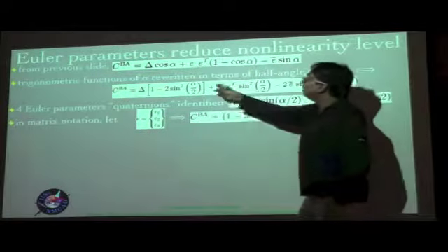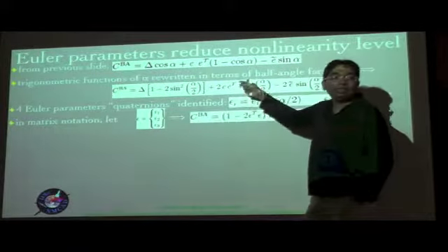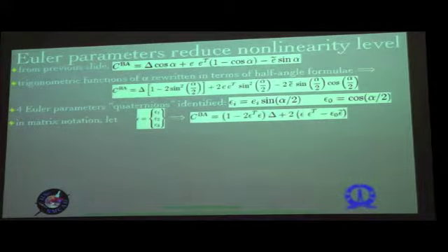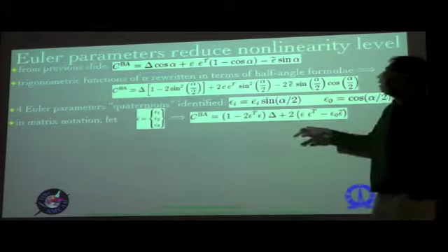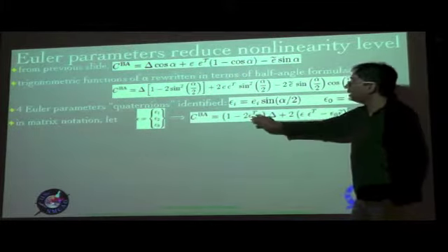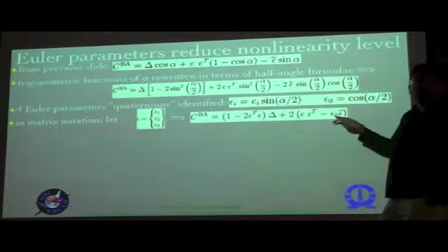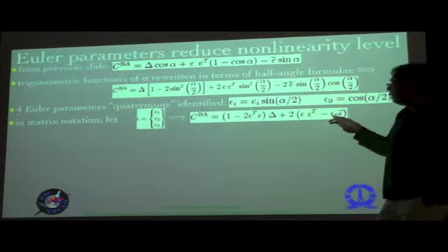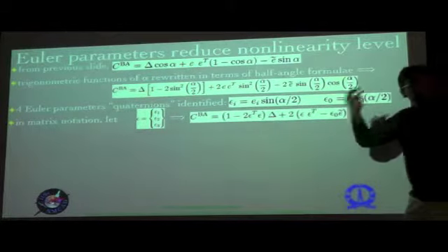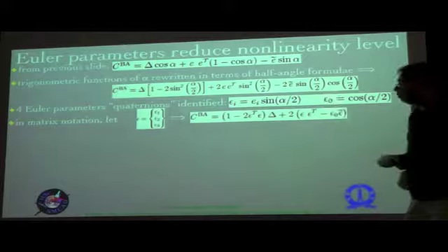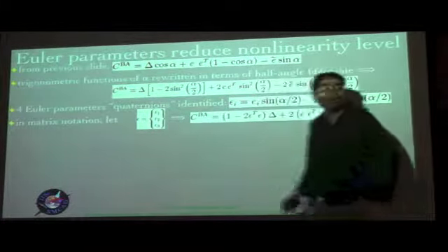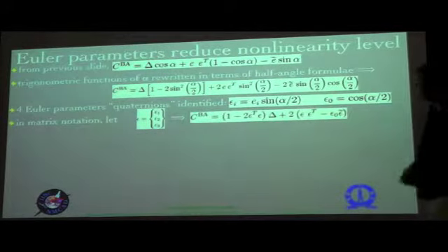So when we do that, you can quite easily see with a little bit of manipulation that CBA, the direction cosine matrix for rotation of B in A, is now given in terms of the 4 Euler parameters, 3 of which are contained in epsilon and 1 of which is floating as a scalar quantity epsilon naught in this particular form. Again, the epsilon tilde holds the same tilde notation that we have been used to, the antisymmetric version of this column matrix, a 3 by 3 antisymmetric matrix.